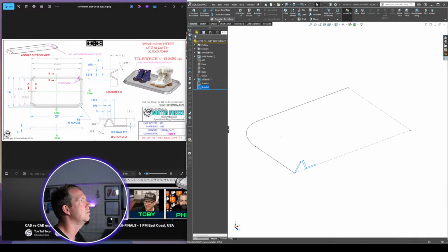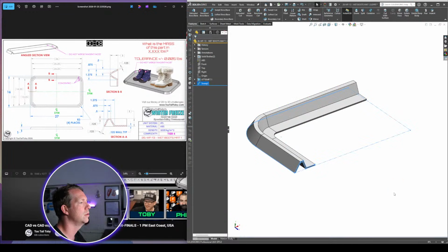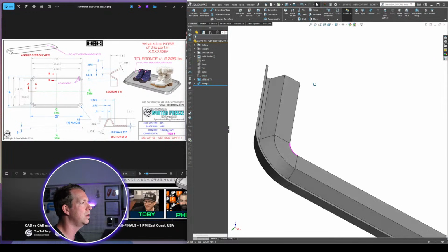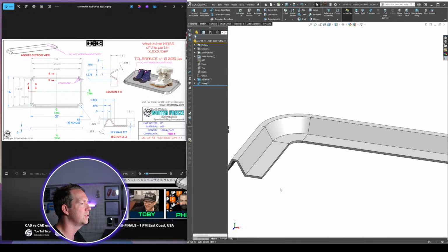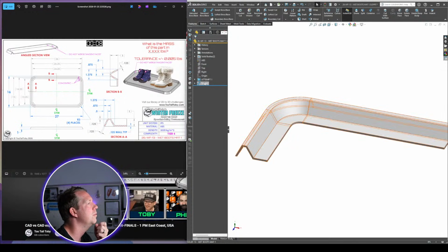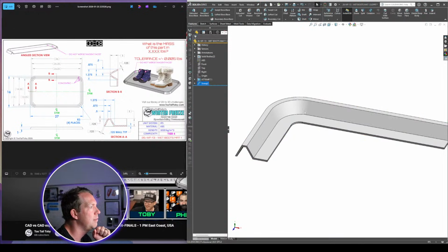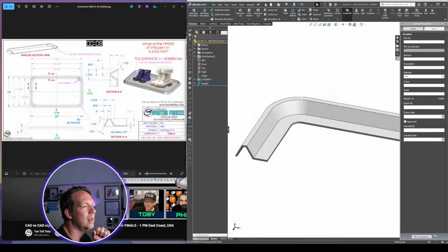So we've got our section. We're going to use our sweep to do that shape. And now that's already got all the inside done for us. And to the Toby note, do not merge tangent faces. That's an option here, which if you check that, you see it makes this kind of curve here, and the weight I think would be different.